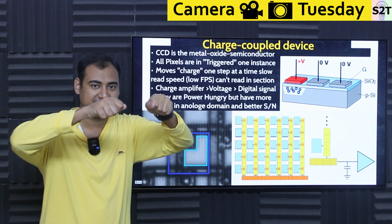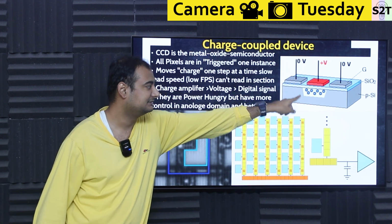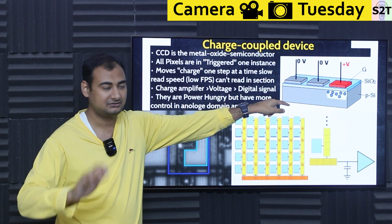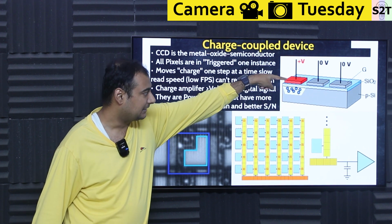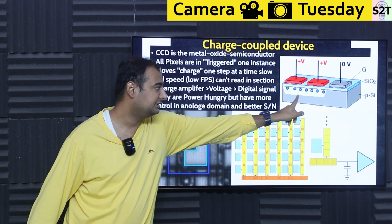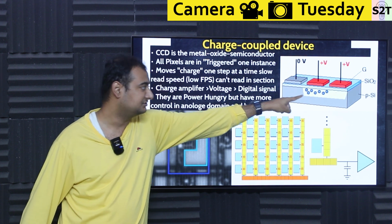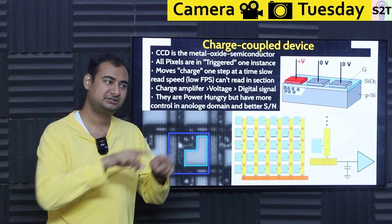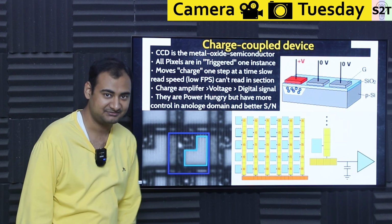It is literally shifting electrons one cell at a time. So you can see you took it. Basically, you have 3 units. Each unit can get either positive voltage or 0 voltage. So you start with 0 volt. You absorb everything, absorb photon, you add positive, it creates an electron attraction, then you switch the positive to the second cell. Now it distributes, then you shut this off, it coagulates here, and then you repeat the cycle again. You start it on, dilute it, concentrate it, move it, dilute it, concentrate it, move it, dilute it, concentrate it, move it. And if you have a 2 megapixel sensor, calculate how many times you have to do that.